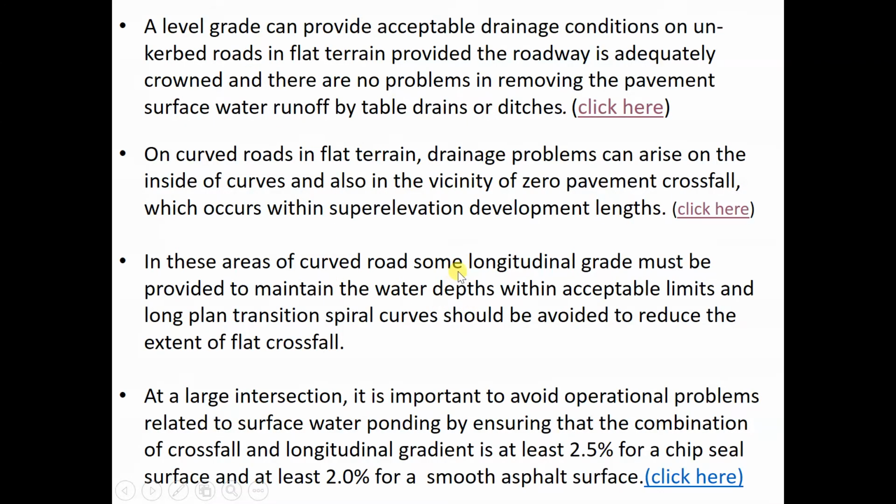In these areas of curved road, some longitudinal grade must be provided to maintain the water depth within acceptable limits, and long plane transition spiral curves should be avoided to reduce the extent of flat crossfall. So for the curved road, it's good to provide some sort of grades. For the longitudinal grade, we say the minimum is like 0.3%, 0.5%.